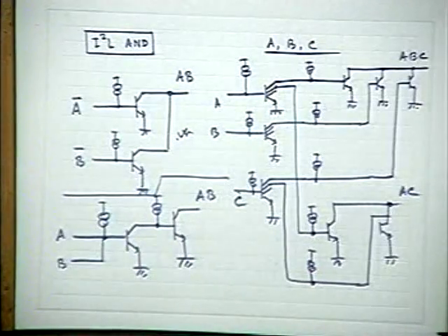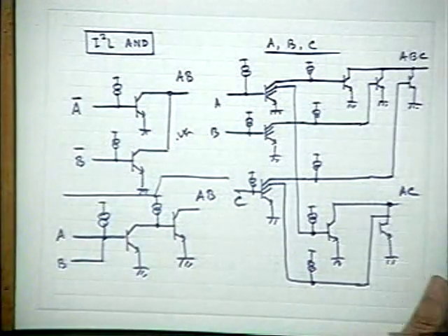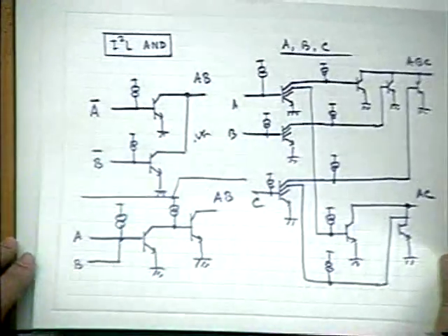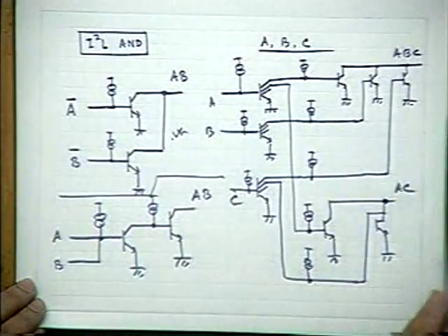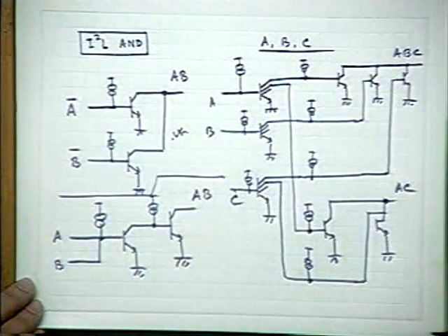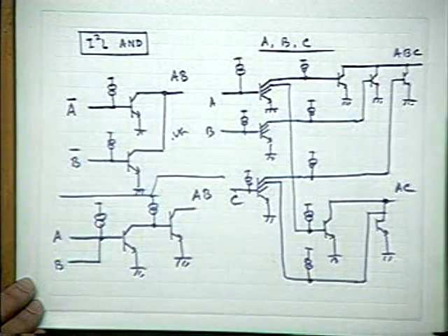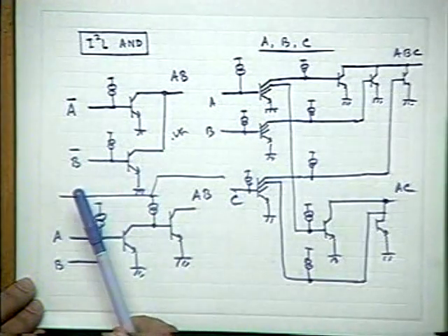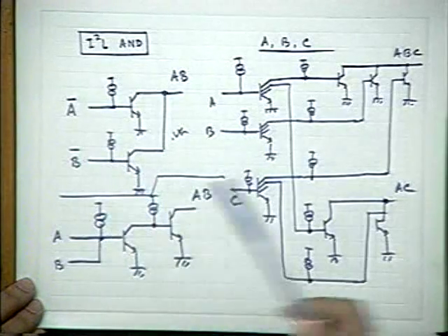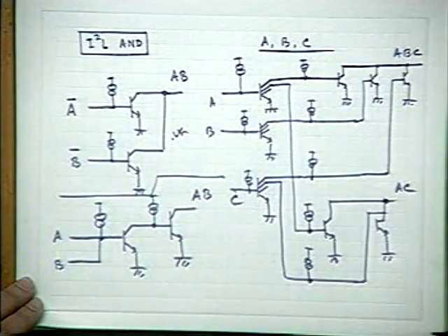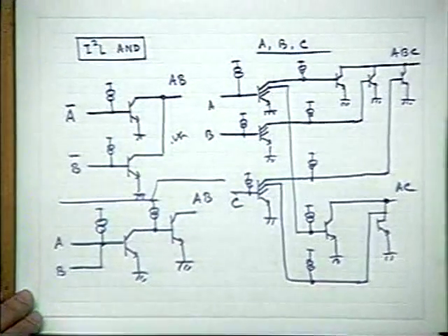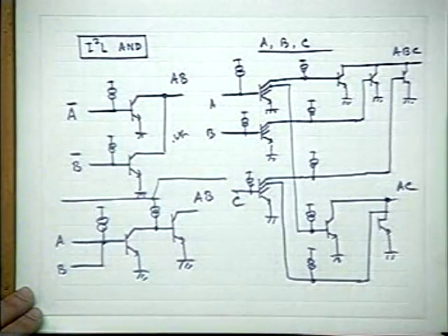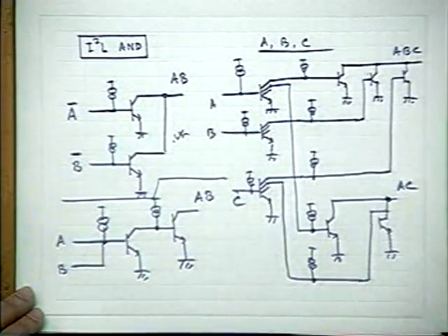I could also use the other approach, but then we need further isolation, another isolation at the back. This is a standard technique for AND gate realization: complement the variables, short the outputs. Similarly, you can generate all the other functions, whatever you like.